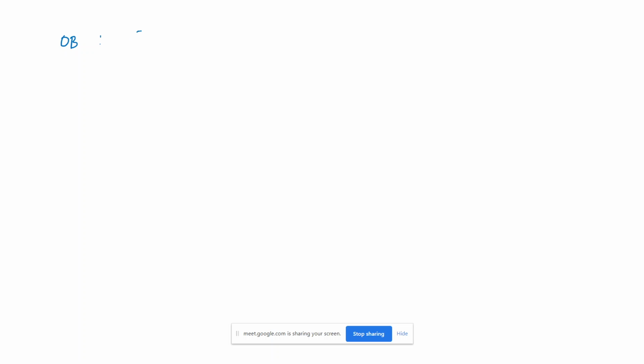The objective function is to minimize the cost, to minimize the summation for i equal to 1 to n of Ci Pgi. This is the objective function, and subject to the summation for i equal to 1 to n of Pgi equal to Pd. We need to meet this demand.